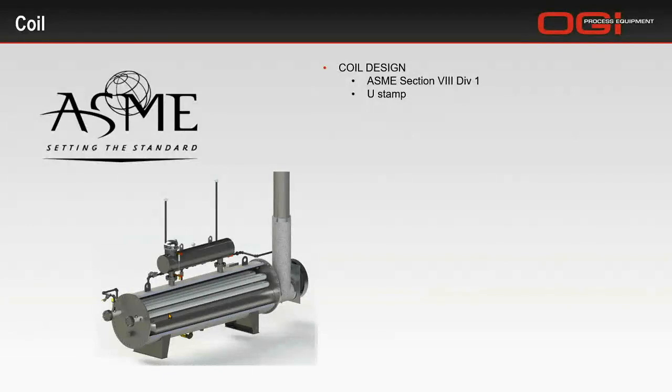weld maps. And one thing that we've noticed is that some customers are now asking for heat maps in addition to weld maps. And I would say that as a manufacturer, we'd like to know this up front. So put that into your specifications. It's not really a big deal to provide it, but if you've already fabricated and welded everything together, being able to go back and hunt down where the heat numbers are will be pretty tough. So let us know up front. We have no issue providing that.